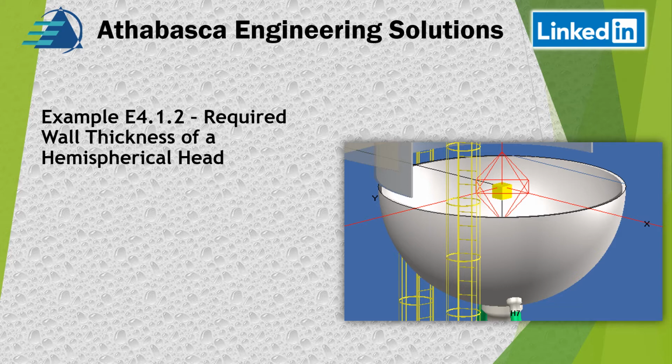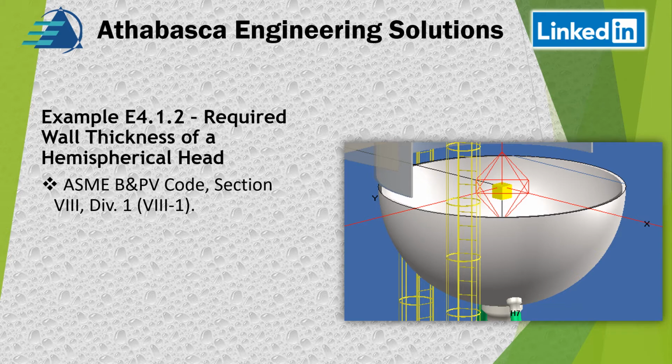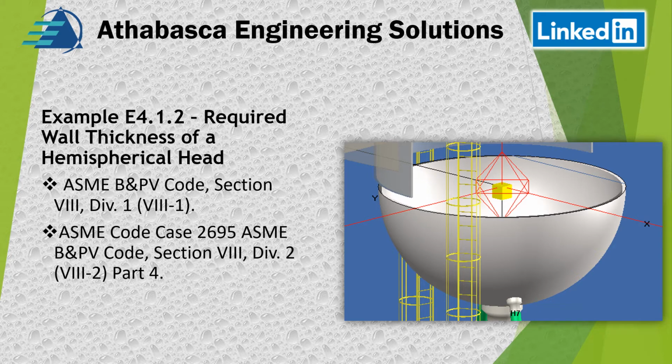We're following ASME Boiler and Pressure Vessel Code Section 8 Division 1, and we're going to use an abbreviation for it. Little is known that there's a Code Case called 2695, and I've never used that, but apparently you can use Part 4, which is Division 2, the alternative rules.